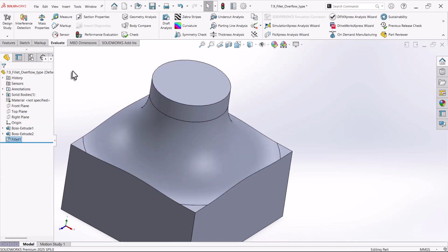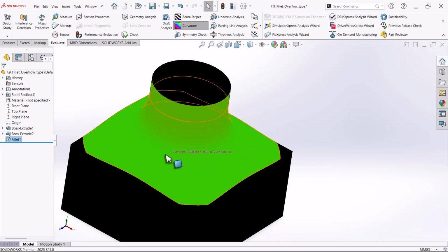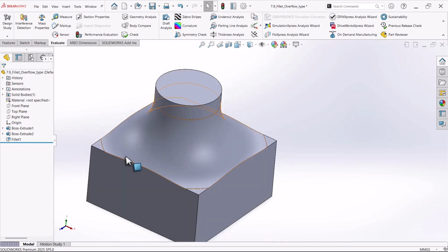Again, let's go to evolute and click on curvature. Here, if you see, in most of the cases the fillet curvature value is maintained. That is 15. When you come across a situation when the fillet value is too large to accommodate within the two surrounding edges, then you need to decide which option to keep, whether keep edges or keep surfaces. But most of the time SolidWorks takes the decision because of default options. If you are not happy, you have to choose manually yourself.